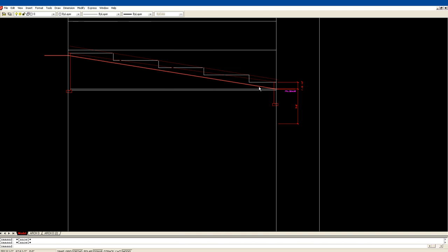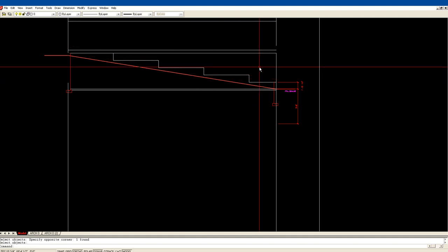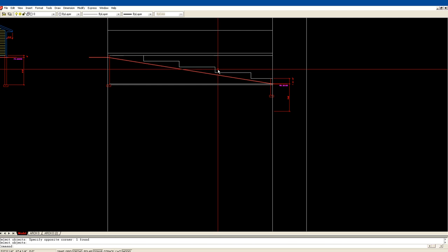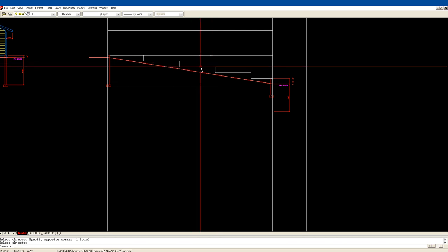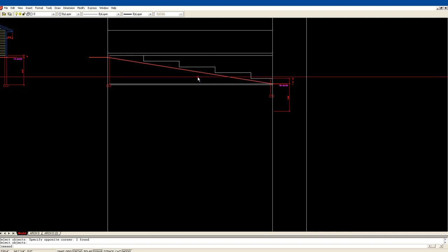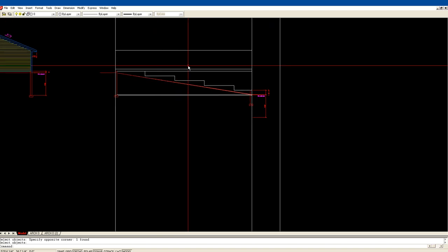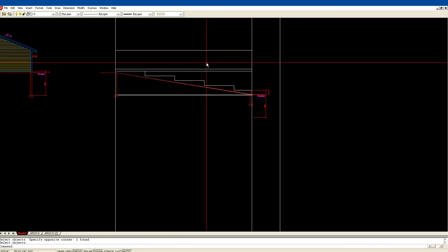So this white jagged line that I've drawn will be the concrete wall. From this concrete wall, he will just use framing up to the bottom of his floor, which was this line right here, and he will go down. So we can erase this construction line and that construction line. Now again, how he digs this is up to him, but what we're showing is to code, and we will label that with a note that says no more than 24 in this direction, no more than 24 in that direction. When he actually digs his hole, this may all change, but as long as he adheres to the code in the label that we put on here, he'll pass inspection. So that's the side of the house.